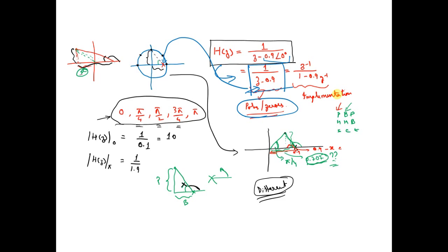First one is delay, second one is adder, third one is multiplier. There is no component for z. So we have to convert this equation such that we have the delay. When we multiply by z to the power inverse over z to the power inverse, we get this equation, and this equation is used for the implementation of the filter.